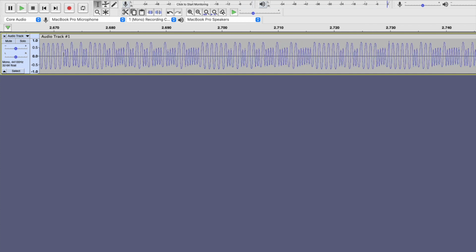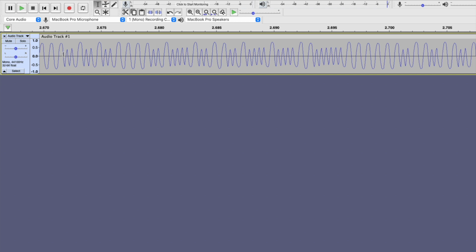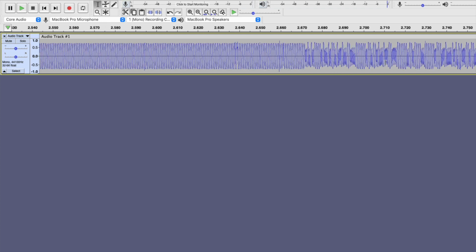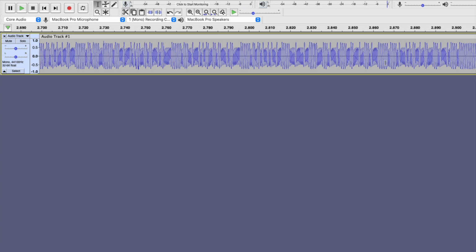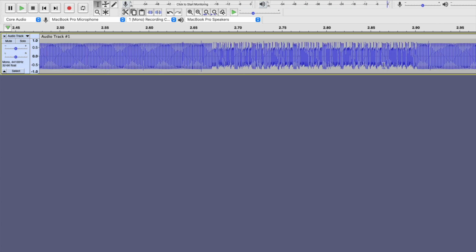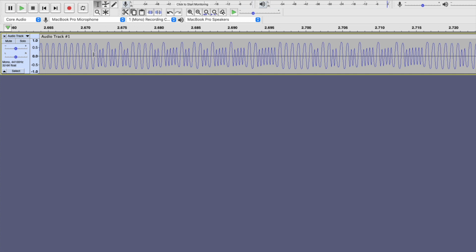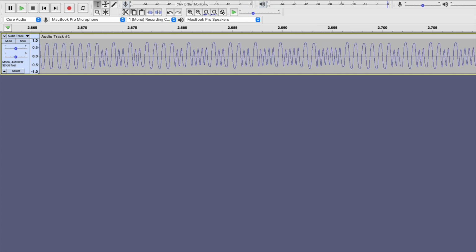Of course, it's easy for us to see that first we have 2 short waves, followed by a long wave, but the computer can only detect the falling edges and the zero crossing, and then use that to determine if the period was above or below a number that represents the middle frequency of 1800 Hz. 2 pulses above 1800 Hz count as a 1-bit, and 1 pulse below 1800 Hz counts as a 0-bit. Since we don't need to recover the clock like Lancaster's bit buffer, or with a PLL or something like that, this works just fine on my 6502, and the BBC Micro for that matter.